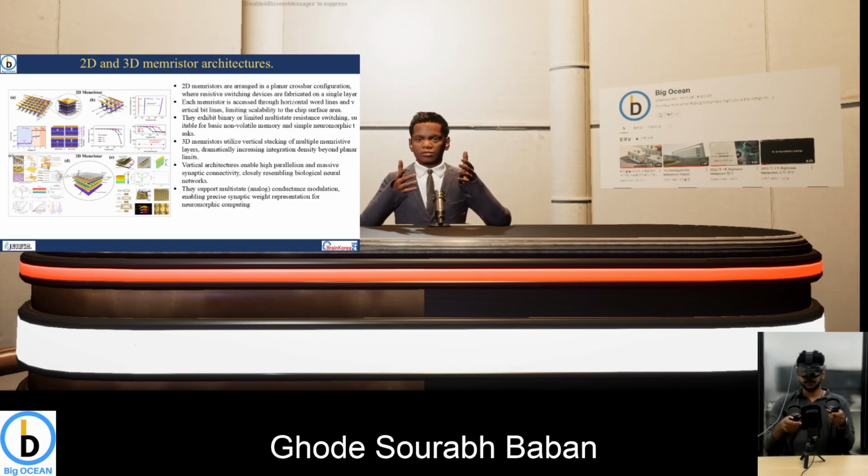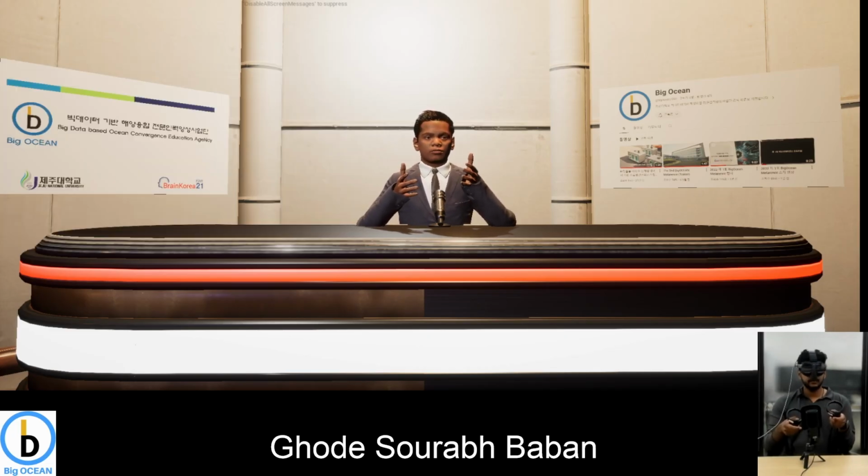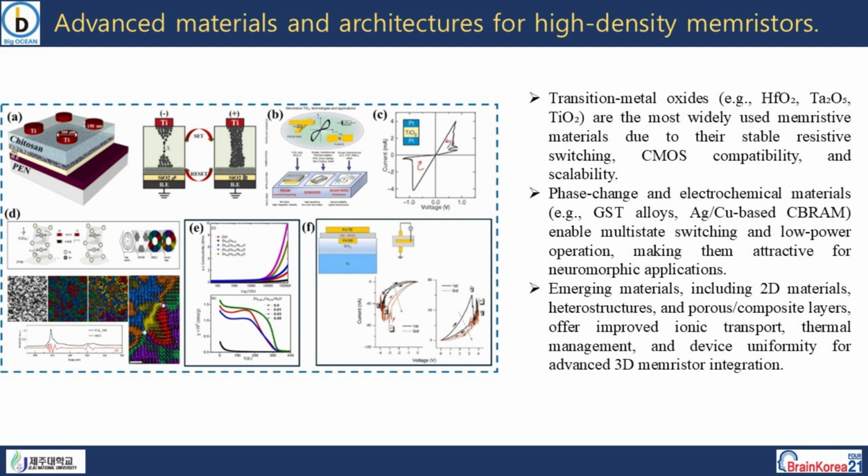In the case of 3D memory, it utilizes vertical stacking of multiple memory layers, dramatically increasing the integration density beyond the planar limit. The vertical architecture enables high and massive synaptic connectivity, closely resembling biological neuron networks. Also, they can support multi-state behavior such as analog conductance modulation, enabling precise synaptic weight representation for neuromorphic computing.